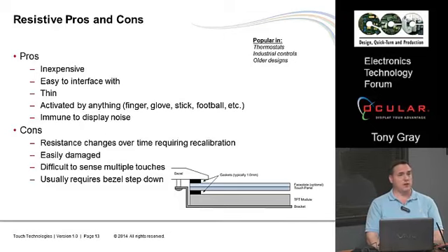Both of those issues, the fact that it can be easily damaged and that resistance changes, are really inherent in the resistive technology. There's just not a lot you can do about it. So if you really want cheap, you can go with resistive, but you've also got to think about maintenance costs, you've got to think about industrial look if somebody writes on it with a pen or whatever, you've got to think about what the environment is, if somebody wants to clean it with alcohol or some heavy-duty abrasive cleaner, it's not a good idea. There are all kinds of issues that you have to worry about.